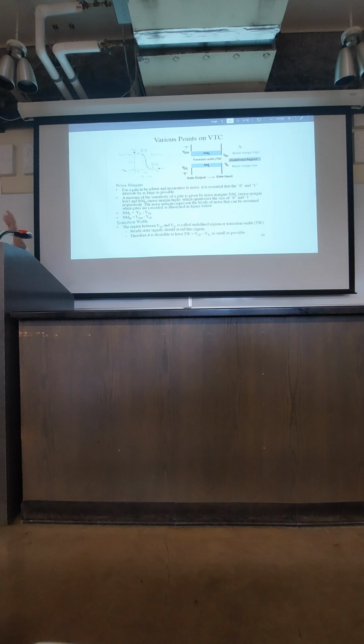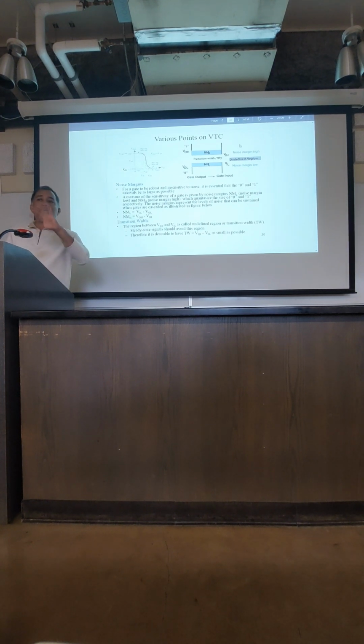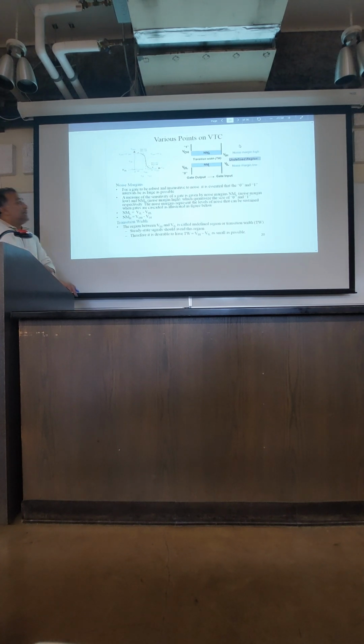Noise margin means the maximum amount of noise a circuit can tolerate without having the signal flipped or go into the undefined region, or having an error. That's called noise margin. Noise margin by definition is the maximum amount of noise a circuit can tolerate before it gives an erroneous signal. On the other hand, noise immunity means the ability of a circuit not to be bothered by noise.